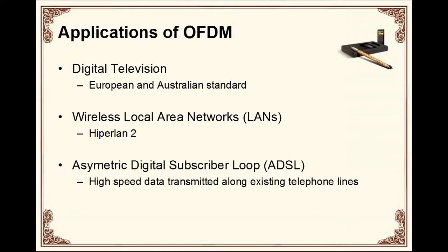There are many applications of OFDM. In digital television, European and Australian standards are using the OFDM technique. In various local area networks, HiperLAN/2 is a wireless standard using OFDM. It is also used in asymmetric digital subscriber line, so high-speed data can be transmitted along existing telephone lines.